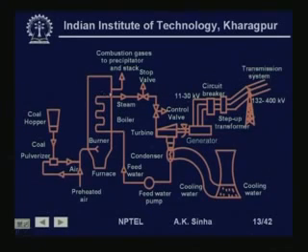Of course, this hot steam here is used to run the turbine, and the control of the flow of steam is done by means of these control valves. In case the turbine has to be suddenly stopped or something, we have a stop valve which opens if the pressure here becomes very large. So, beyond a certain pressure, the stop valve can be used to release the steam out and to bring the pressure in the system down to tolerable levels.